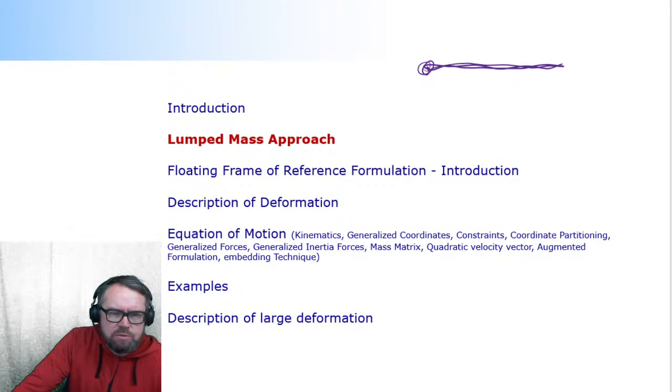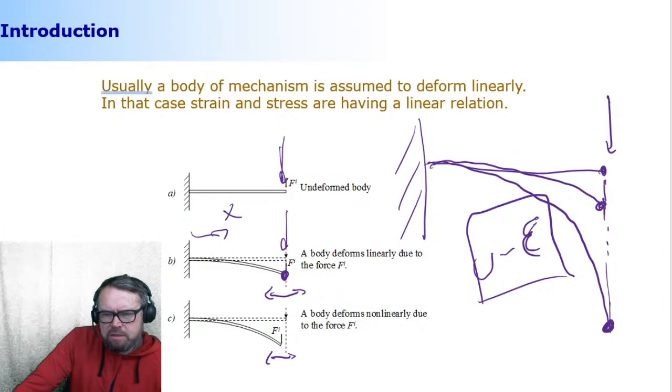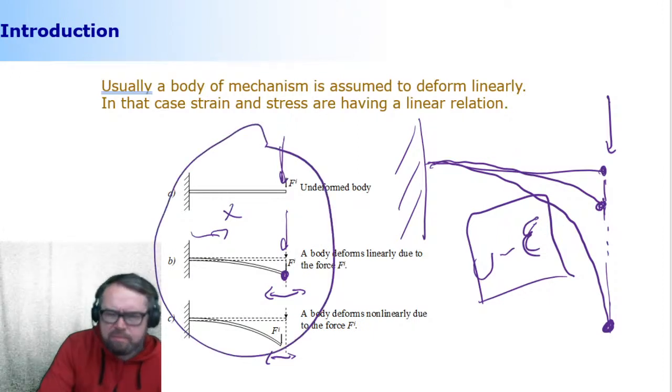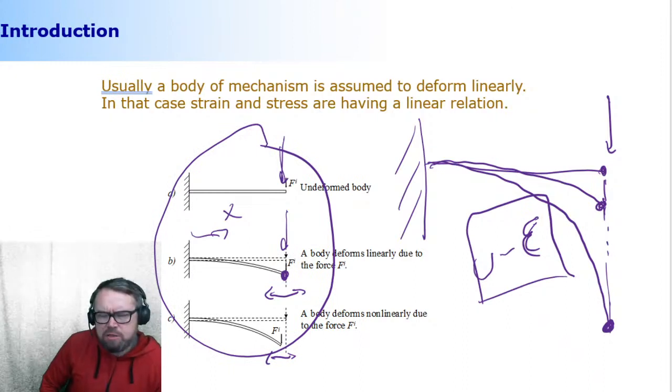And also this one here, if it is related to this cantilever structure, in a cantilever structure, the only thing that makes a difference, I need to see where my pointer is traveling, this one here, this thickness to length ratio. If you look at this behavior, the only thing you can see different here is that something called transverse shear deformation started to make some contribution.